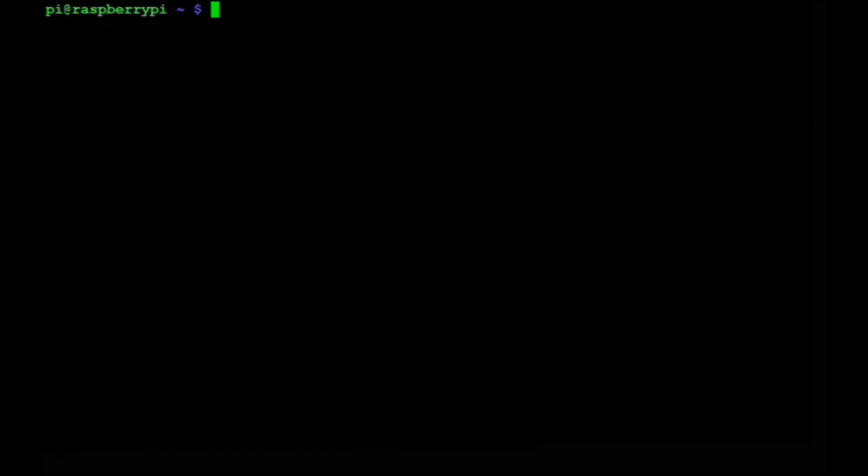We open the terminal window and create a Python script which will output a signal to pin 7 and light the LED for 5 seconds. The script is as follows. We will discuss each line in detail. To create the script we type sudo nano led_light.py.